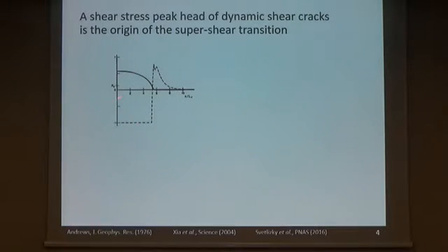So what you see here is basically, this is the crack here. Here you have this small cohesive zone, very thin in this area. This is actually the opening shown in this direction, but it would be more too. And in front you would have the stress concentration. And what you can see here is there's a little bump. This bump comes due to the acceleration, to the initial initiation.